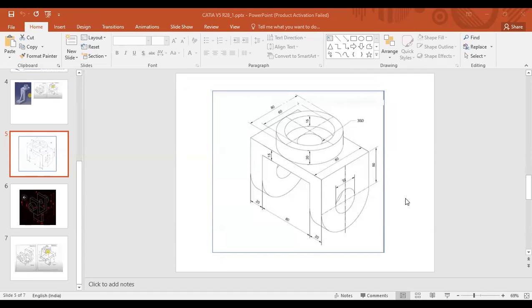this toolbar. If it is a solid line, then this will be considered in the pad, to create the pad. If this is a construction line, then we need this as a reference, but this will not be considered while projecting a pad. Okay, so as of now